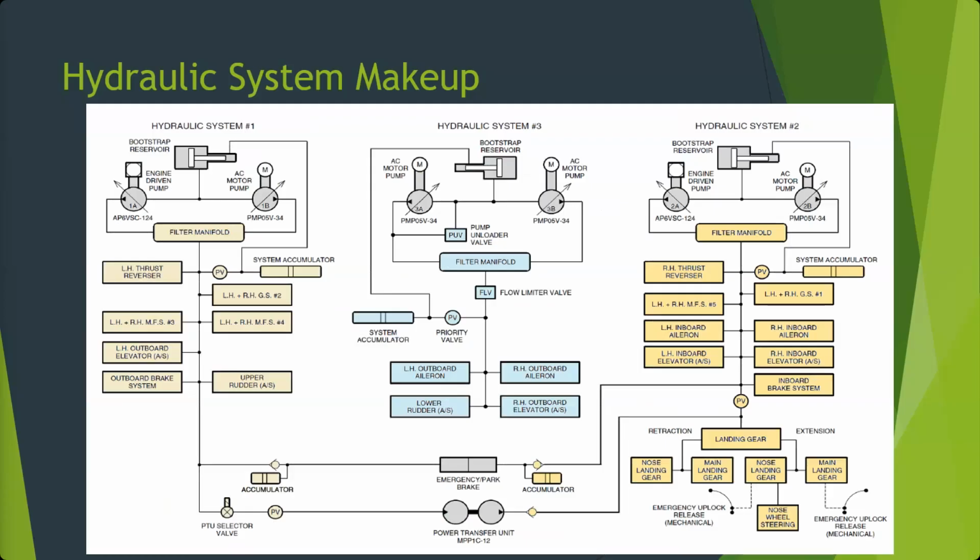Okay. Now, in electrical, we can connect those buses and we can move power. One engine or even an APU can often power everything if need be, depending on the size of the aircraft. Larger aircraft, maybe not. We'll have to load shed a bit. But by having it that way, you've got that redundancy built in, whether it's through mechanical means, through hydraulic means, or through electrical means. Okay.